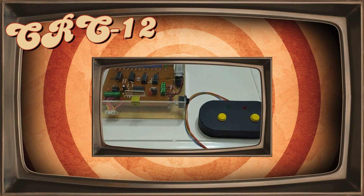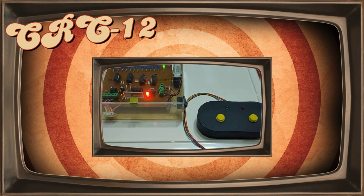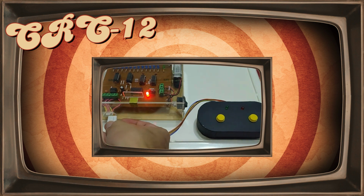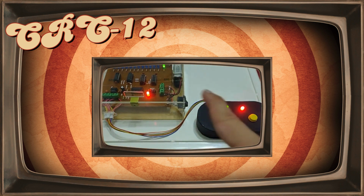Let's actually demonstrate the CRC-12 process by using some input messages as examples. Here's our CRC-12 circuit in close-up view. Let me power it up first. There we have it, and then let me connect the controller right over here in its port. Look at the green LED, they are in sync. The red LED means it is connected. This button right over here is to enter a bit of 1, and this one will reset the whole CRC-12 circuit.